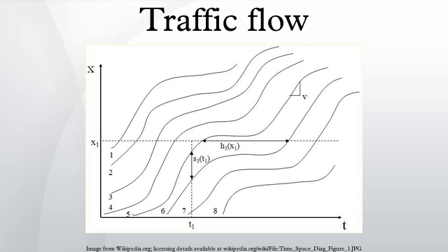Case 2. In case 2 of Riemann's problem, traffic goes from congestion to free flow and the cars accelerate as the density drops. Again, the slope of these shock waves can be calculated using the same formula, V_shock equals ΔQ over ΔK. The difference this time is that traffic flow travels along the fundamental diagram not in a straight line across but through many slopes between various points on the curved fundamental diagram. This causes many lines emanating from point X1, all in a fan shape, called a rarefaction.